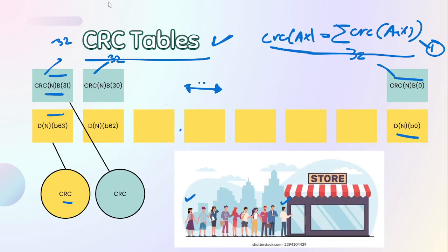And the other thing is that this is the simplest form of understanding the CRC tables, but I don't do it on a bit basis. I do it on a byte basis because tables can easily handle 8 bits. So what I will do is I'll combine 8 of these bits into one byte, right? So a CRC state would be just 4 CRC states.